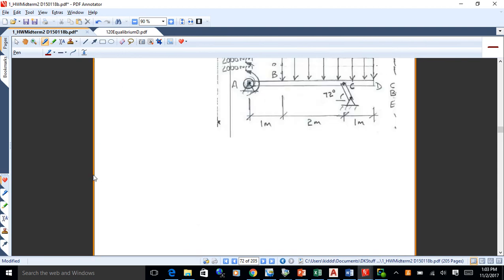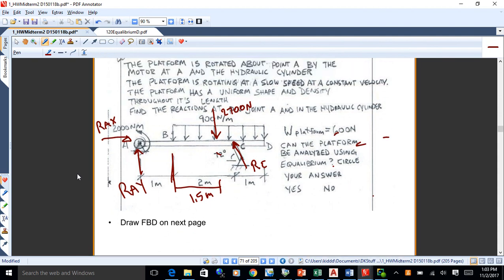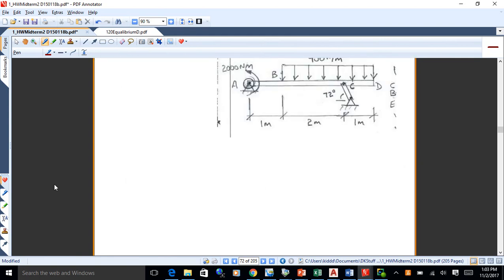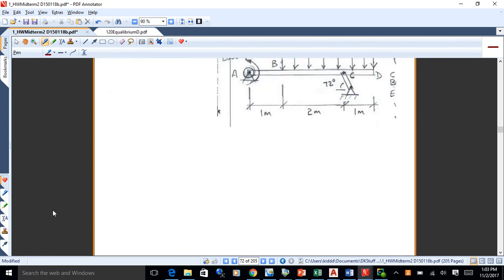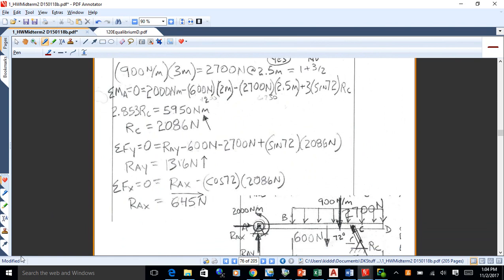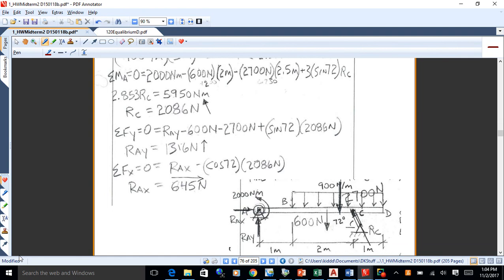So, off you go. You've got your free body diagram. You can take moments about A, and you just go ahead and do that. So sum of MA, you'll have that couple, 200 newton meters, positive. You're going to have the 600 newtons for the platform by 2 meters, right? Negative because it's clockwise. So it's a 4-meter platform, so that 600 newtons is in the middle.